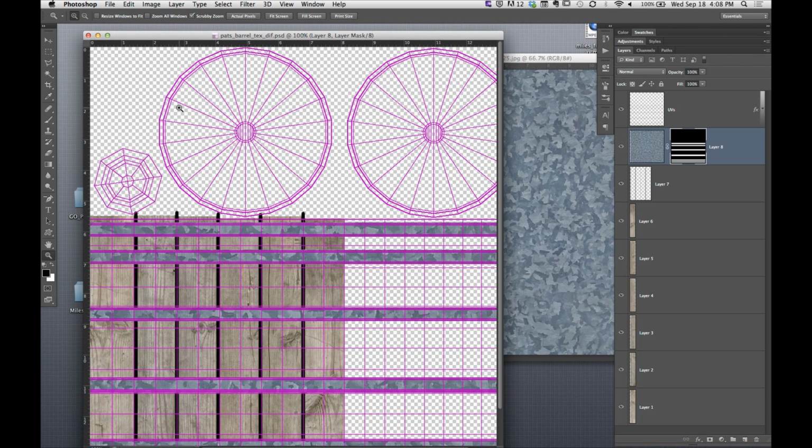It's too big. It's going to crash your system performance. It really does. Photoshop documents can get quite large, especially when you have a couple hundred layers in them, okay? I've had Photoshop documents that are gigabytes in size. I'm not going to load a gigabyte Photoshop document into my 3D app. I need to reduce that into a file that's a little bit more comfortable for the rendering engine to handle. So we need to flatten this.